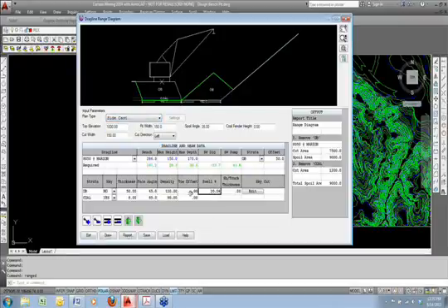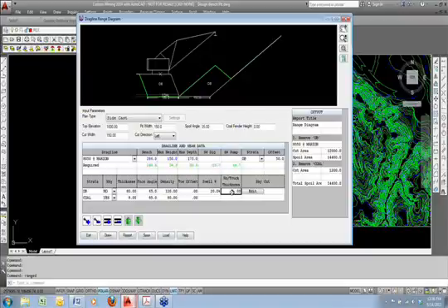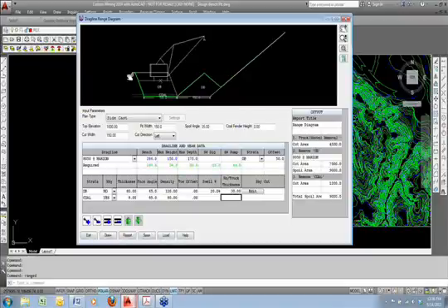So I'll continue now. Let's see, our swell will be 20%. And you're also allowed to do some pre-strip or truck shovel thickness. So of my 50, let's increase that to 80. I have an 80-foot overburden, but I'm going to allow 30 feet of that to be pre-stripped. So that's just taken away, not thrown into the spoil, and I'm now left with 50 of overburden.